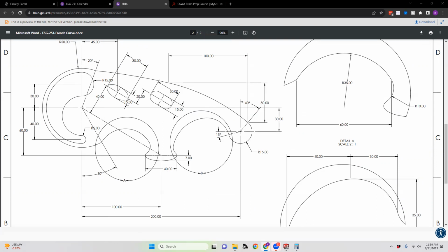Because you've seen how to make measurements side to side like this, and measurements relative to the origin, which in this case is here. The height of something relative to the origin and the distance of something else relative to the origin is really important for getting this kind of sketch fully defined.